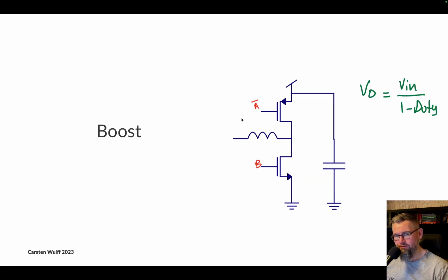You don't have to go down in voltage. You can go up. So if you have a silver oxide 0.8 volt battery, and you need a 1 volt or you need 1.5 volts, then you can boost the voltage. You can go from a low voltage to a high voltage. This is great, for example, for thermoelectric generators, which maybe have a voltage across them of a few hundred millivolts, but you want to power a 1.8 volt system. Well, then you have to boost the voltage, and you can do that also with inductors. It's just a slightly different configuration.